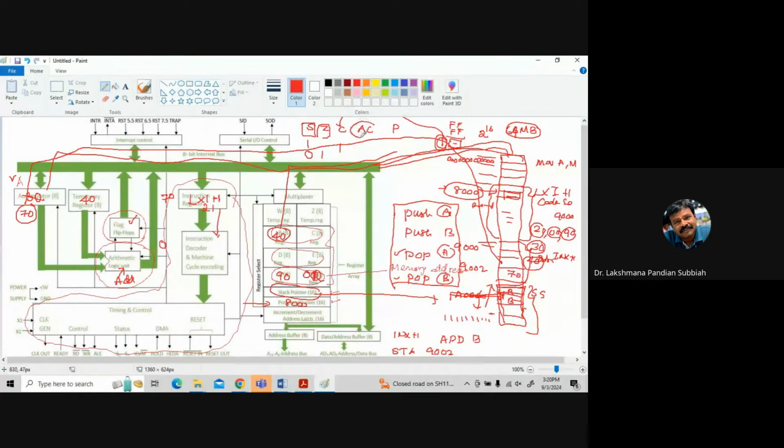The auxiliary carry is used for, we are having it as 4 bit by 4 bit, so the total is 8 bit. Within that 4 bit, if you are having a carry, this is the auxiliary carry. So between the 4 bits, after the 4th bit, the 5th bit we are adding. So this is 1, this is 1, we are summing that, that is 0, then we are making an increment, and that is going to make the auxiliary carry. This auxiliary carry is used for adjusting hexadecimal to decimal change.